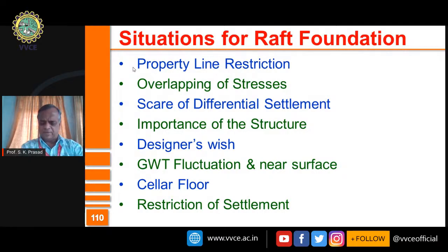We don't want settlement to be maximum. We want the settlement to be well within the tolerable limits. Sometimes settlement may be more at some places, less at some other places, and so on. When you have a situation like this, in order to balance, in order to provide more or less uniform settlement, you need a solid slab at the base, and that is when you resort to raft foundation.